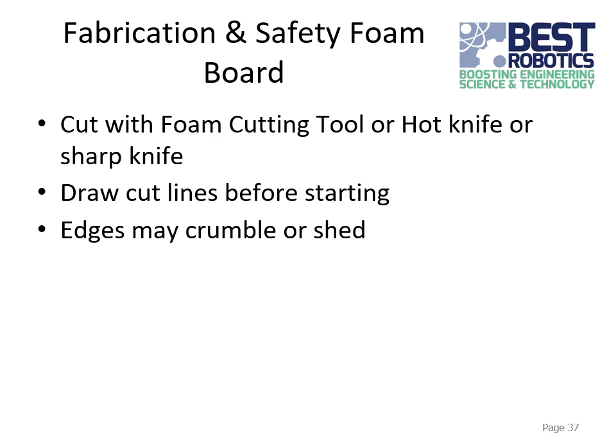With foam, make sure you're marking your lines before you start, so you know exactly where you're cutting. If you're using a regular knife, sometimes the edges can crumble or shed, like little chunks of it will break off as you're cutting it. And so the edges may look kind of rough. So it's up to you whether that's important or not. Sometimes it doesn't matter that much depending on what application you're doing.